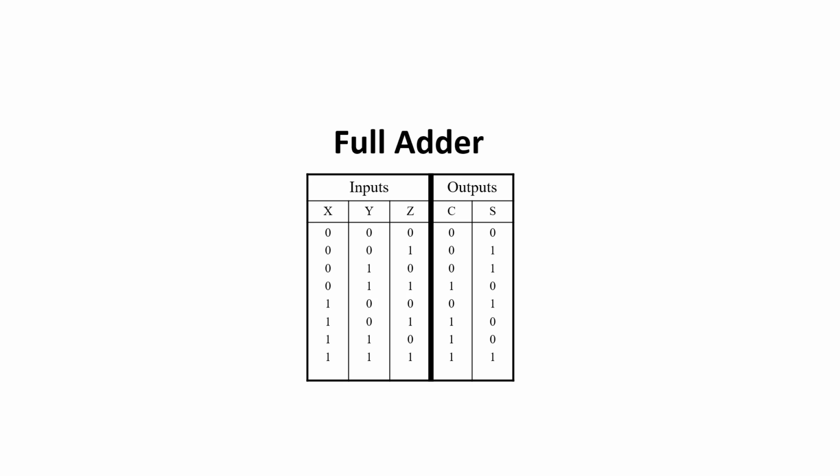So now I'm going to use this decoder in order to build the full adder. Remember that we did the full adder before, and we mentioned it has different designs. One optimized design was two half adders and an OR gate, or you can use the original equation to build this function. But now I'm going to use the decoder and some OR gates to build the full adder.